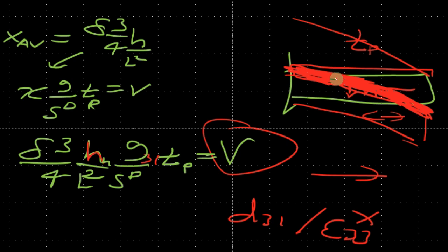The piezo becomes more stiff. You won't get as much displacement because you're increasing this H. Oh, it'll be harder to deflect. You'll need more force to deflect. Right now we're using the relationship between deflection and strain. However, you'll get less deflection if your piezo is thicker. So just different things to note, and if you want to optimize or whatever. But this works pretty well.